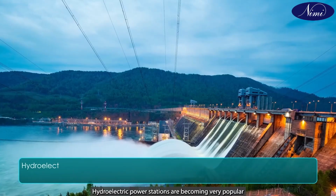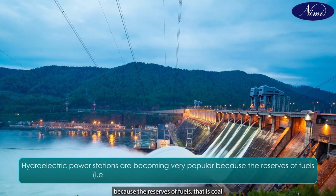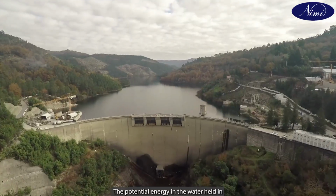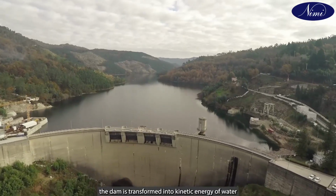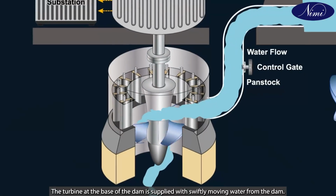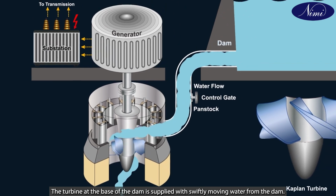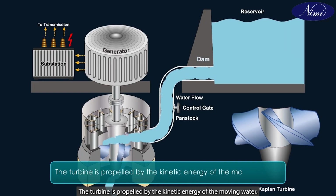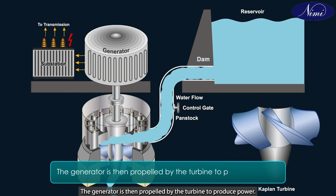Hydroelectric power stations are becoming very popular because the reserves of fuels, that is, coal and oil, are depleting day by day. The potential energy in the water held in the dam is transformed into kinetic energy of water in hydroelectric power plants. The turbine at the base of the dam is supplied with swiftly moving water from the dam. The turbine is propelled by the kinetic energy of the moving water. The generator is then propelled by a turbine to produce power.